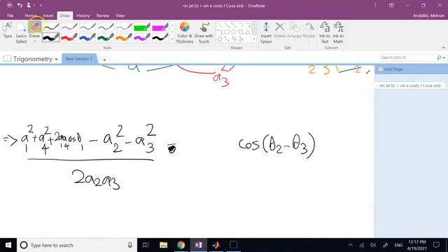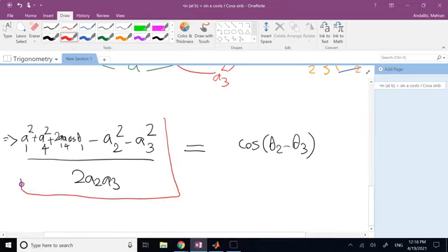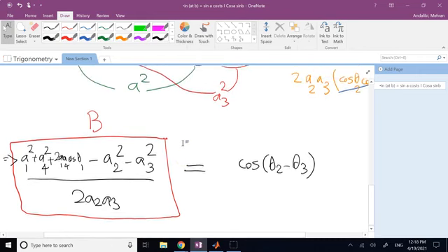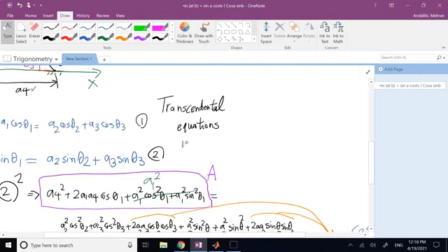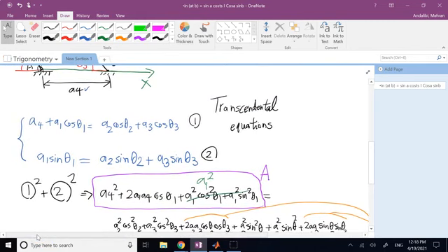And now this guy here, I can call it whatever you want. Does not matter. So I can call this whole given number B. So now the cosine of theta 2 minus theta 3 is a constant, so I can take cosine inverse from both sides and find the difference between the two angles. But I also need another equation that can help me find what? Another relation between them, and then combine the two to find theta 2 and theta 3.